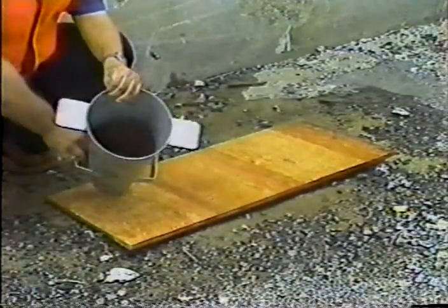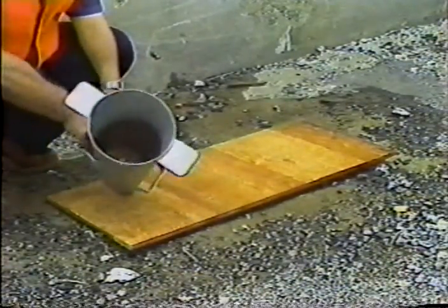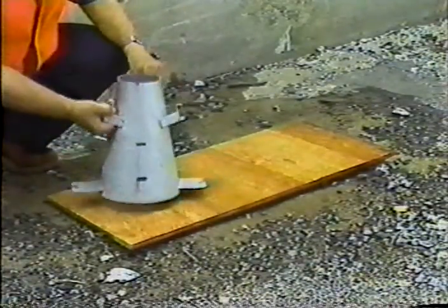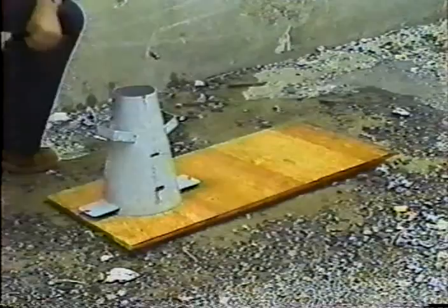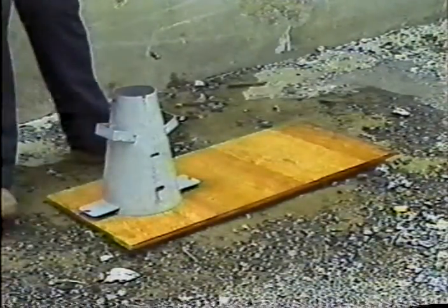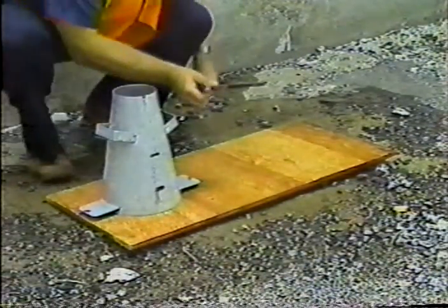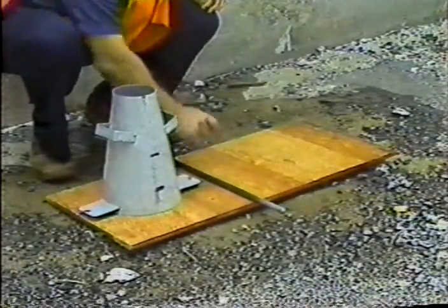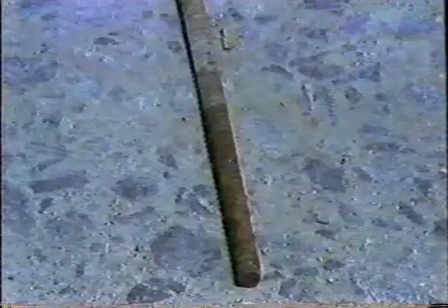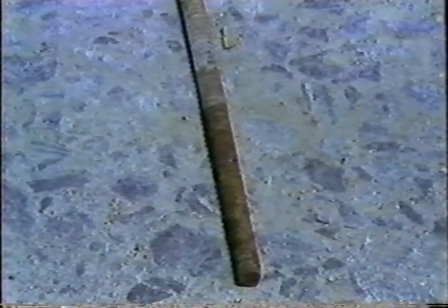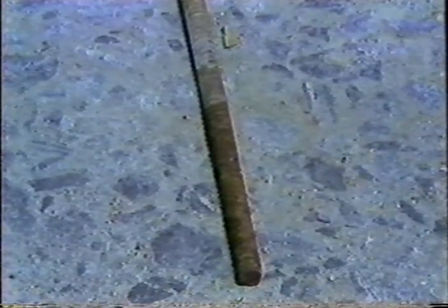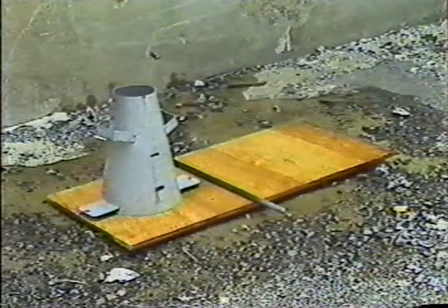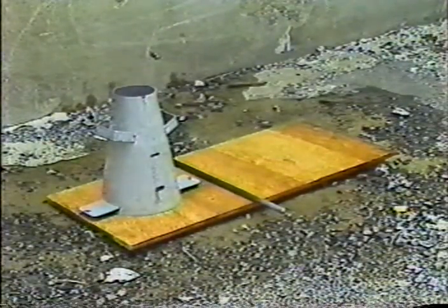Second, a standard slump cone. It should be reasonably clean with no major dents. Make sure the inside is smooth. No dried concrete. Third, the tamping rod. Make sure it's the standard rod, made for concrete testing. It's not acceptable to use a cut-off reinforcing bar instead. The rod has to have a rounded tip, so that the large aggregates aren't pushed to the bottom when the concrete is being rodded.